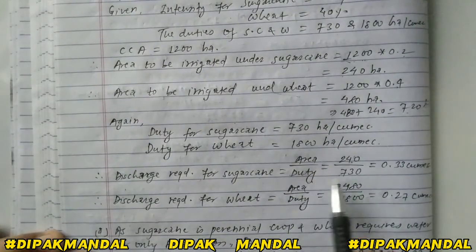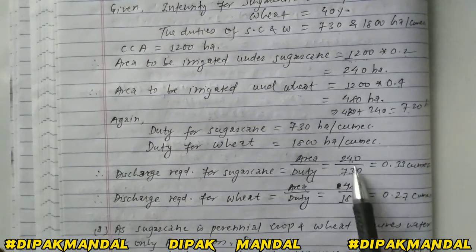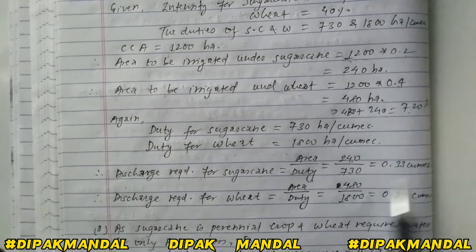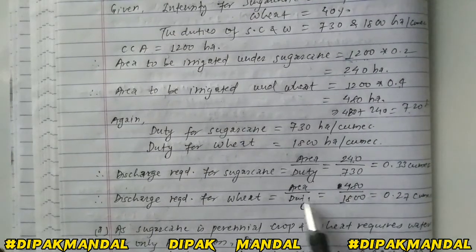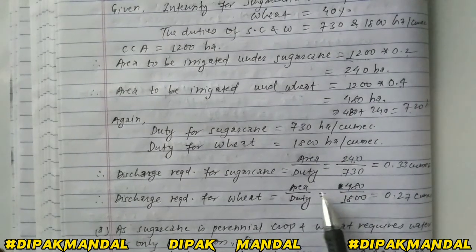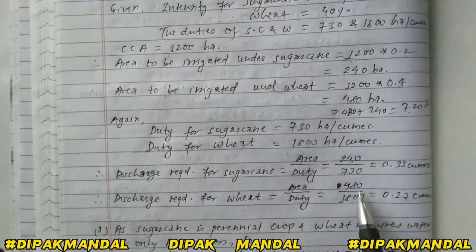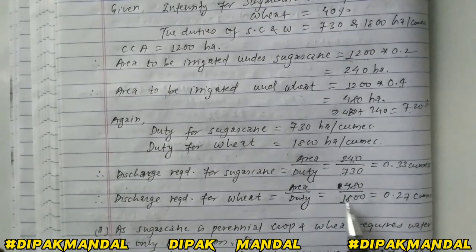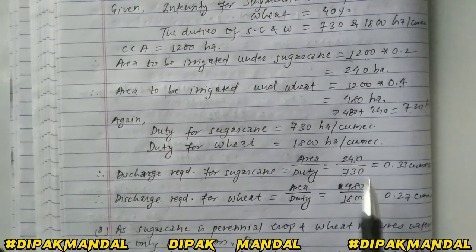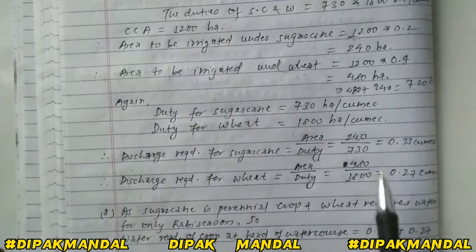Okay, for getting discharge, we get the value of discharge for the sugarcane equal to 0.33 cumecs, and for the discharge of wheat equal to area by duty, as we did previously for sugarcane. The value of area for wheat is 480 hectares, which we have calculated, and the duty is given in the question, that is 1800 hectares per cumec. So that value is taken here.